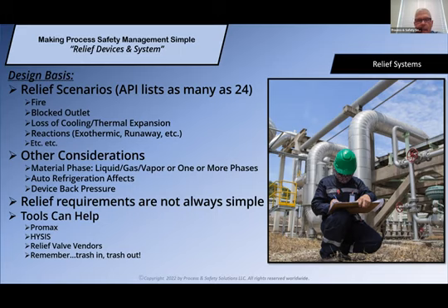We know, and we should know, that a relief valve will respond, or its capacity is different, given what media is flowing through it, if it's gas or liquid. We must evaluate any auto refrigeration effects. For example, if you're relieving propane, we know that that pressure drop is going to create issues with icing downstream, perhaps, or other situations, depending on where it's relieving to.